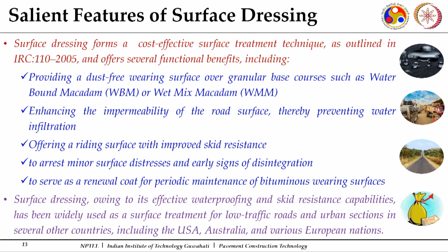So what several benefits can we derive out of this kind of treatment? It provides a dust free wearing course, because you seal the surface with a thick film of bitumen, especially on rural roads or low volume roads where you normally use waterbound macadam or wet mix macadam. Then it enhances the impermeability of the surface, because a thick film of binder is put over it, offering a riding surface. And as I said, the texture is open, so it gives a good skid resistance also.